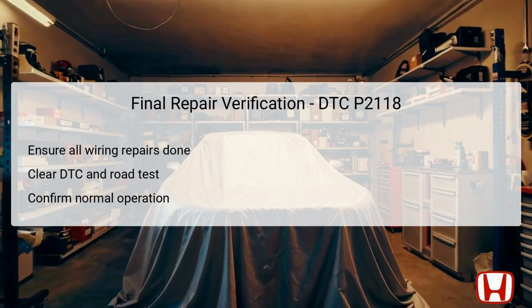Conducting a final repair verification after addressing DTC P2118 is crucial to ensure proper functionality has been restored. First, verify that all wiring repairs made throughout the troubleshooting process have been executed correctly. This includes ensuring that every connector is securely reconnected and free from any corrosion or damage. Once confirmed, utilize the HDS to clear the DTCs once again from the system, which will reset any fault indicators